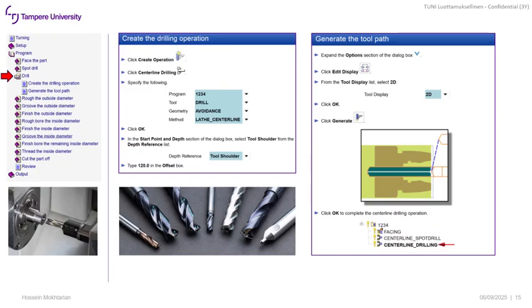our drill. From the geometry that we have for this tutorial, the final diameter of the hole that we need to make is actually 20 millimeters, if I'm not mistaken. So in that case, we can consider that it can go with one single pass of a final diameter of 20, but it's not really easy to say so. It really depends on the specification of the parts and the material quality and also the tools that we are